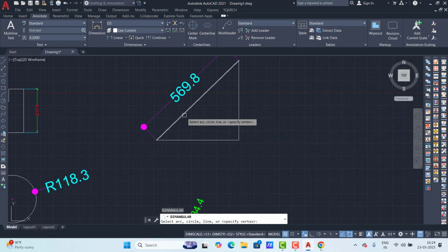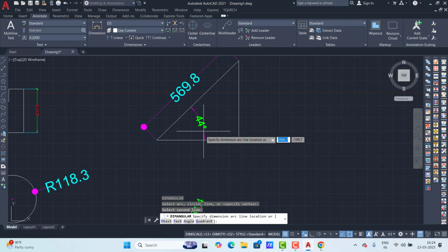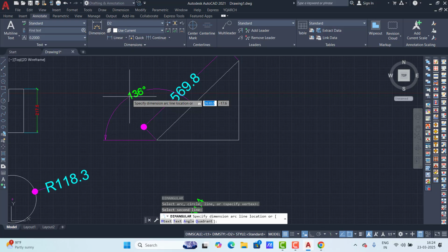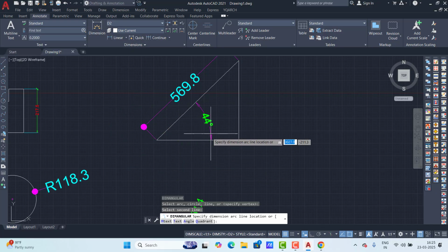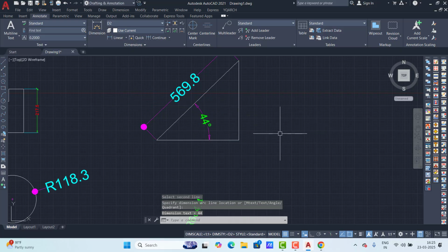When you press enter, see here, the starting point is this one and we have to give only the second point. So here we give the second point. Same if you want a third point, we can give the next point, and the next. Any points can be different, but the starting point is taken from this one. So this is the baseline option, and you can press enter.